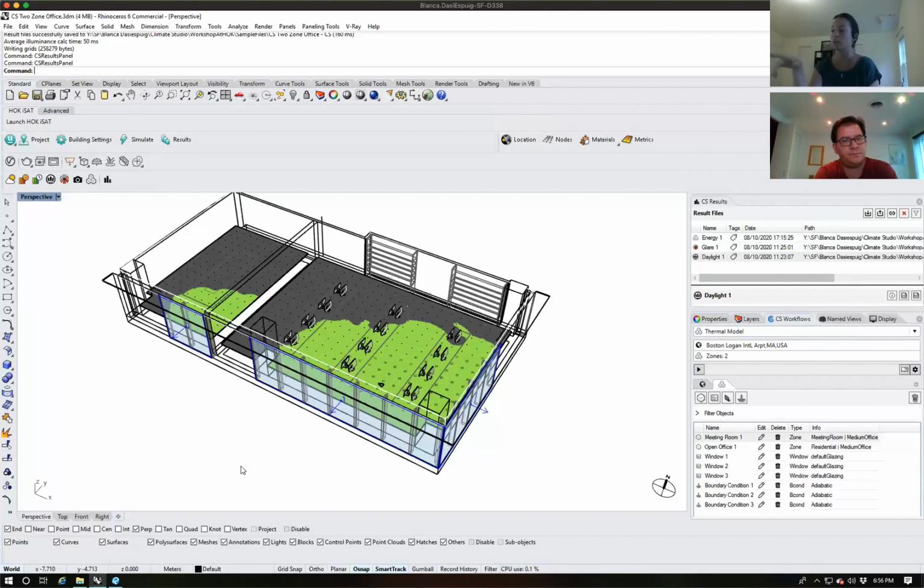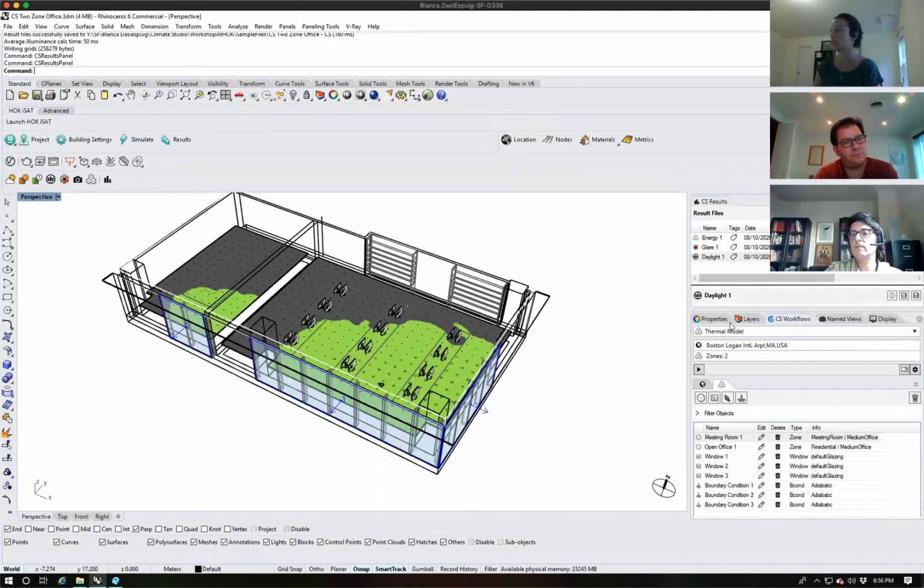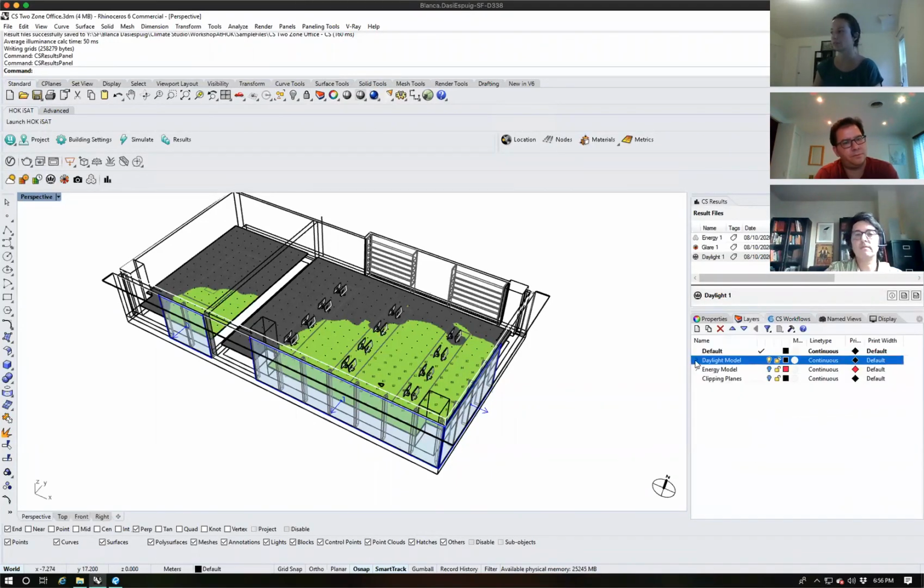With this one, the only thing that you would have to do is just get rid of the Revit blocks. A lot of the times, the blocks are part of things that you don't need, whether it's furniture or mechanical systems or fixtures and things like that. If there are still some blocks that you want to keep, you just explode the block and leave it at that. And the only thing that you would need to do is sort out your layers.